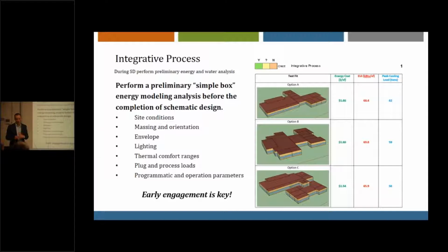Looking at operational parameters, like, we also work on a lot of medical office buildings. You might have one part of the wing, and that's actually what this example is, that needs to operate way later than the other parts. So what does putting that on a different HVAC system do? The main HVAC system doesn't have to run all the time. So it's been great for teams that actually want to meet the intent of this credit and get the point.